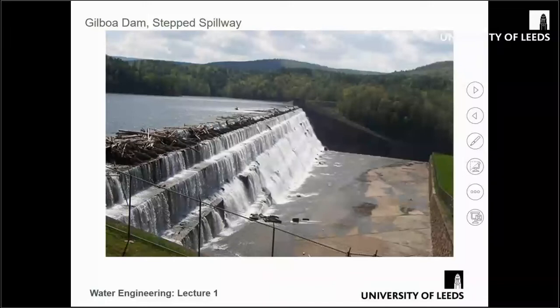And this is for the rivers, the reservoirs full. We need to say, well, how much water goes into it? How big does this weir need to be, so that once the reservoir's full and the water's still flowing in, how big does this overflow need to be to allow enough water out without the reservoir getting too full? Okay. So it's designs of structures like this.